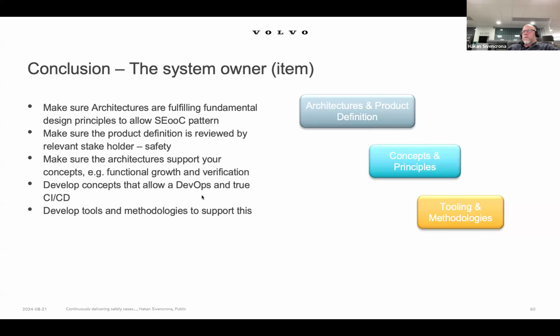And you also need to be aware that sometimes you think that you don't need to take safety expertise into account when you're setting something up. ABS, for example: you have a very good function, and then please implement it safely. What I mean here is that safety engineering will become a really integral part of doing the product. ABS, it was, okay, please don't let any systematic faults happen here. Don't let any random hardware faults happen more than this often so that we lose our ABS, for example. But now safety needs to be a more integral part of it.